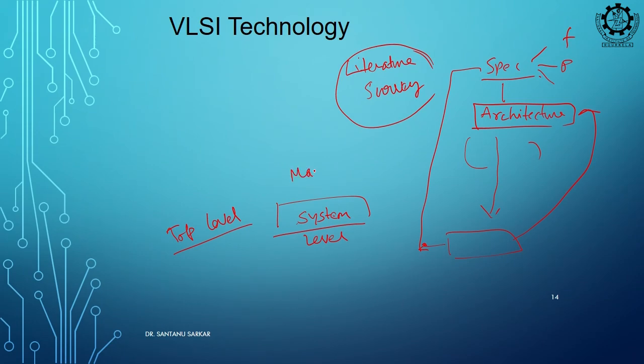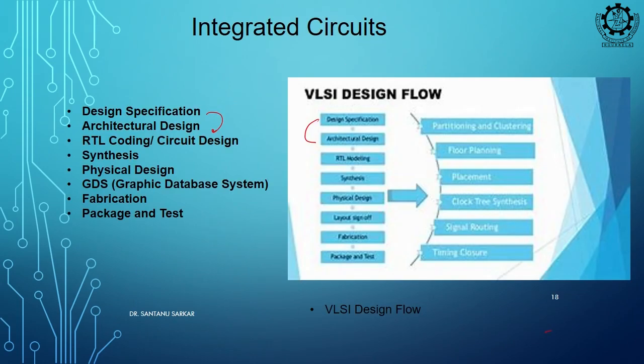For example, whatever the mathematics of your architecture, you code it in MATLAB or some other tool, maybe in Simulink, or maybe in SPICE you make it very top level, just define the mathematics and quickly check whether this system or architecture is able to achieve the specs or not. So, at each level you will be doing the cross check, so that you are not wasting a lot of time and then at the end finding out that this is not suitable. This is generally the flow.